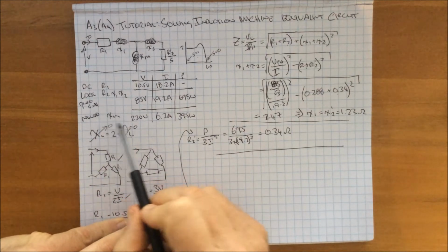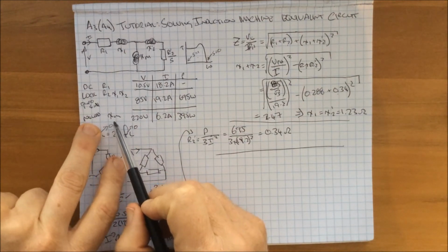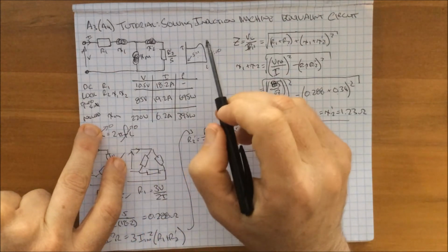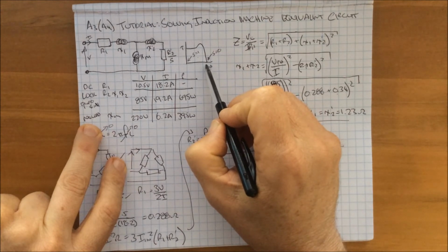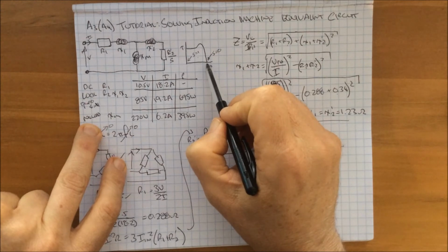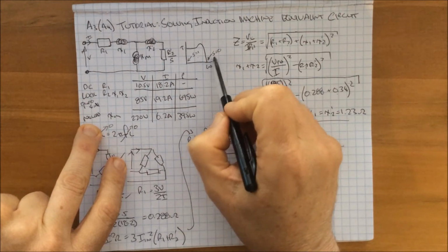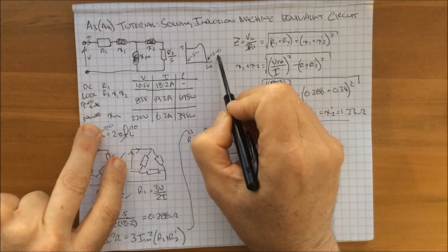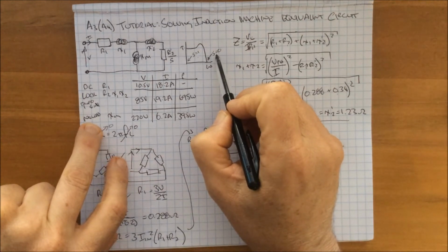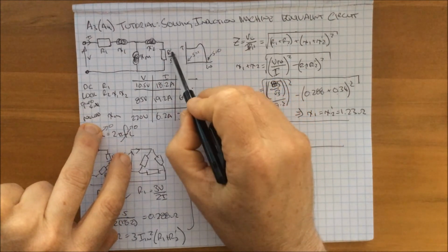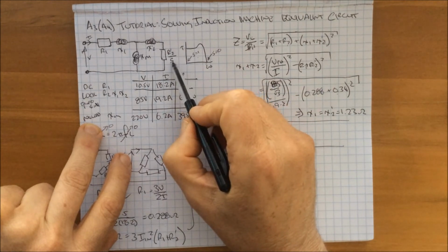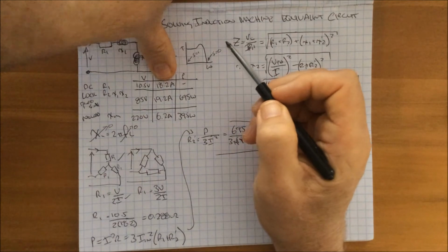we go to a no-load test. In our no-load condition, our speed is up here. Our speed is at the maximum speed, and so therefore the value of slip is not quite zero, but close enough to zero for our third approximation that we will assume it is zero. By assuming that slip is zero at no-load speed, anything divided by zero is infinity. So our circuit now becomes this.